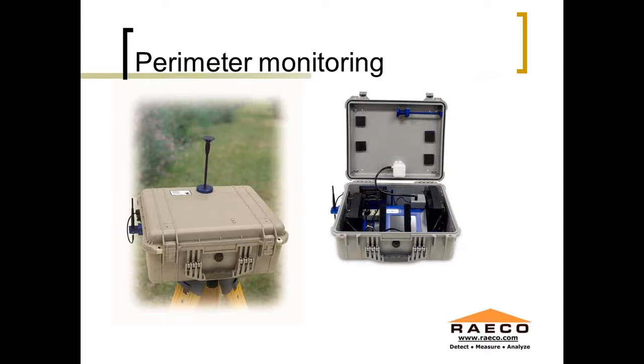And sort of the area where we see the most focus now would be perimeter monitoring. This picture right here is just an example of our solution for outdoor monitoring. What we've done is we've taken a Pelican case and we've retrofitted it for outdoor monitoring. On the top of this case you have an isokinetic probe. That isokinetic probe allows for a sample to be pulled into the Pelican case without any kind of water or anything entering into the enclosure.